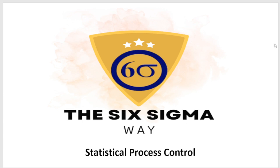So in today's video we are going to talk about statistical process control, which is often called SPC. SPC is a technique that utilizes statistical methods to monitor and control the process. So we monitor the process over time to check the consistency and prevent defects, and also to make decisions based on data analysis.